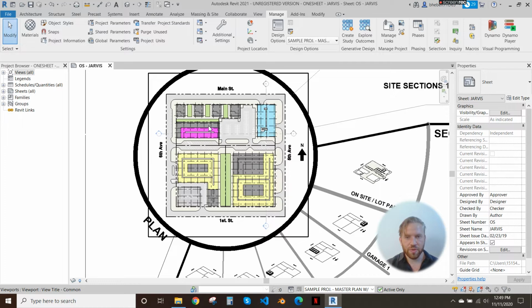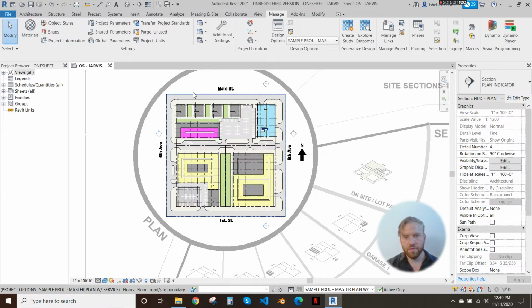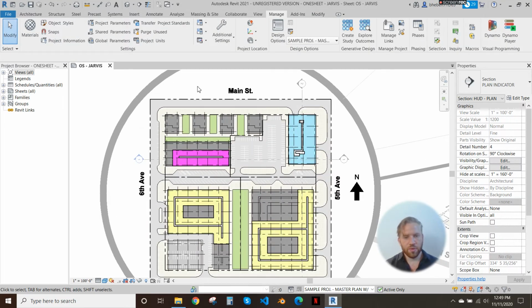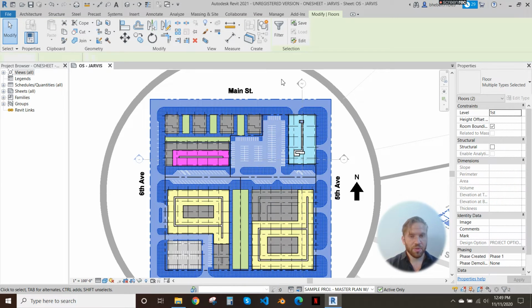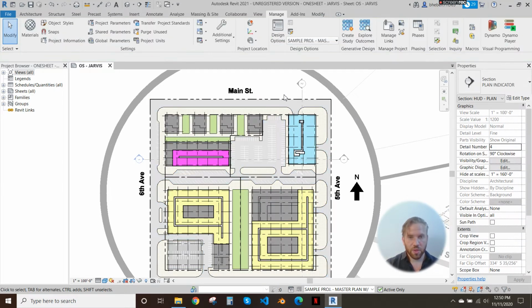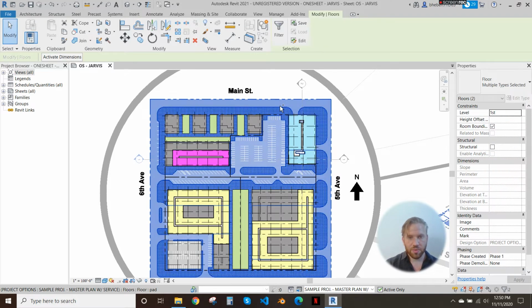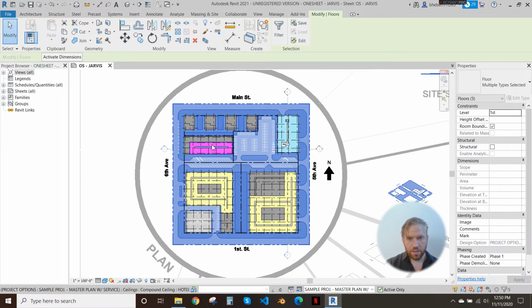So what we want to do first is double click into the plan view here, and you'll notice when you select things, if you also hold the control button, you'll be able to select multiple things. So select one thing. This is going to be the road right here. Select the road. Select this curb. All comes as one chunk. Building pad and curb. Select these green planes here, and just make sure that it turns blue once you have these things selected, right? So this helps you understand what you have selected.